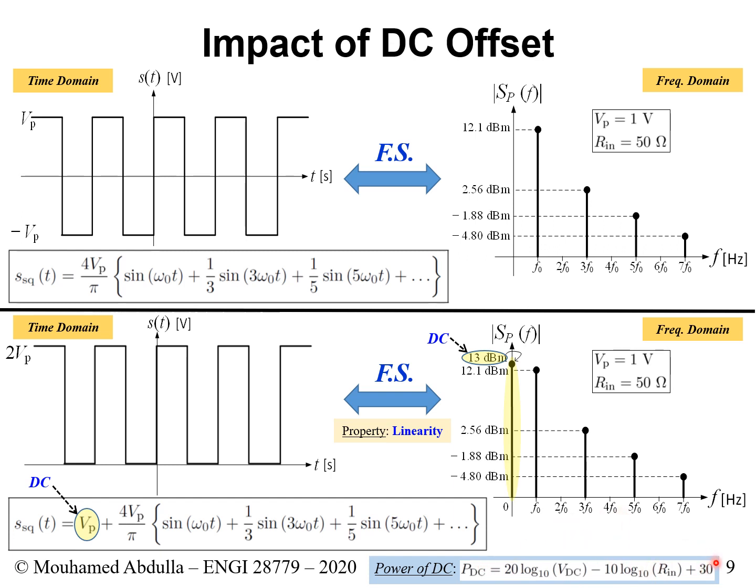And in fact, you will need to show this. I didn't have time or space to show it on this slide, so I'm going to just show you the result. So it is 20 log 10 VDC, whatever it is. So in this case, our VDC is this thing here. So we would enter this, minus 10 log 10 RN, plus 30. Notice it's no longer plus 27. Plus 27 was for these ones. This is plus 30. And it's increased by 3 dBs because we don't do the square root of 2.